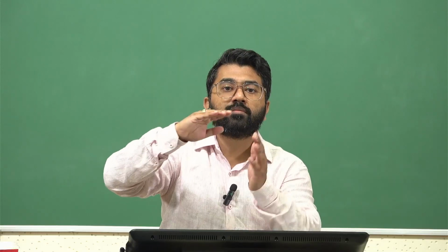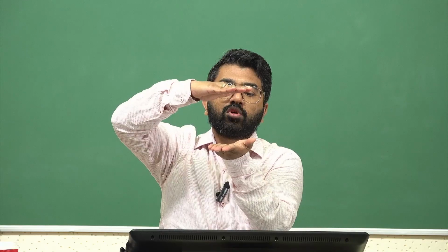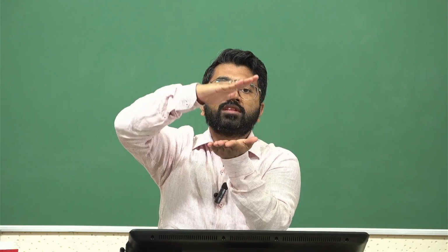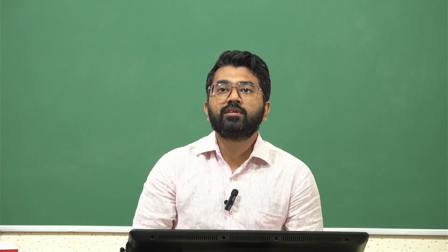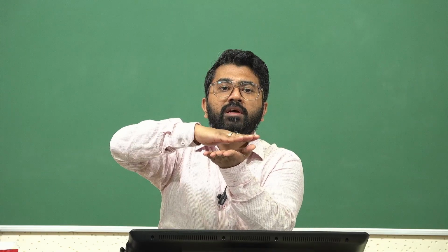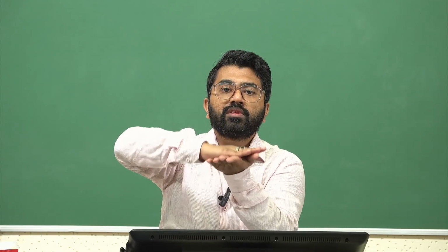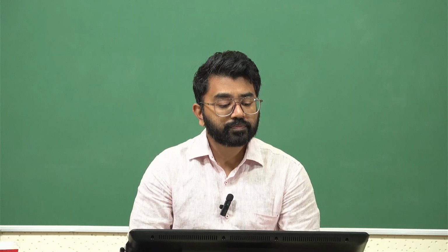The bottom clamp is usually fixed, right, and the top one moves. But how much can it move? There can be certain limits which are set, because certain soft tissues like the brain tissue, if this is the bottom clamp and this is the top clamp, can very easily get crushed and the clamps can collapse against each other. So you want to set limits so that the clamp automatically stops when it has come, let's say, 2.5 or 3 millimeters within this vicinity, just to make sure these kinds of tests do not lead to damage of the machine.